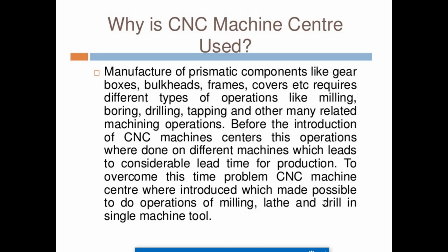If you go for manufacturing of prismatic components like a gearbox, you can look for an image of a gearbox to see how much complexity there is. We have bulkheads, frames, covers, etc. All those things that make up the gearbox are very complex to manufacture, and it requires different types of operations, like milling, boring, drilling, tapping and many other related machining operations.